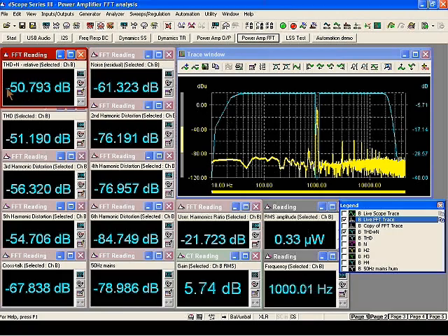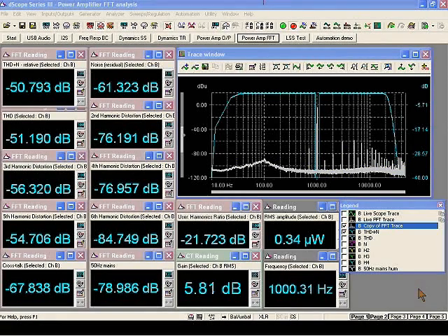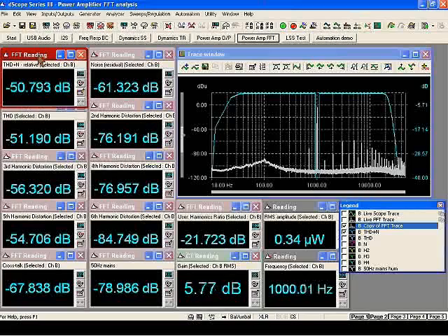So let's start up here. One of the measurements that I'm measuring here, and was measuring live before I captured this result here, is THD plus noise. I'm just going to turn on a previously measured result where I've actually done a bit of averaging here to clean up this trace a bit. You can see that THD plus N is reading minus 50, nearly minus 51 dB. How is that being measured? Well, we're implementing this light blue, this turquoise notch filter here, removing the 1K component prior to integration of the remainder of the signal. And you can see that this is an ideal, a perfect brick wall notch filter, which is something that you can't do with the kind of real-time analysis instruments that we saw earlier and perhaps you may be familiar with.